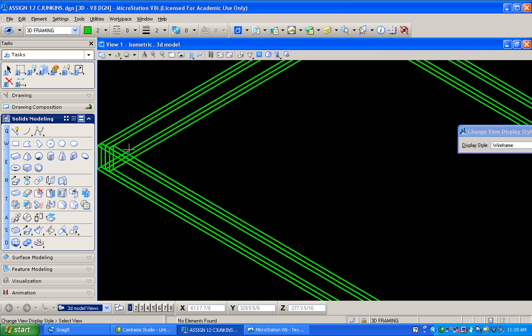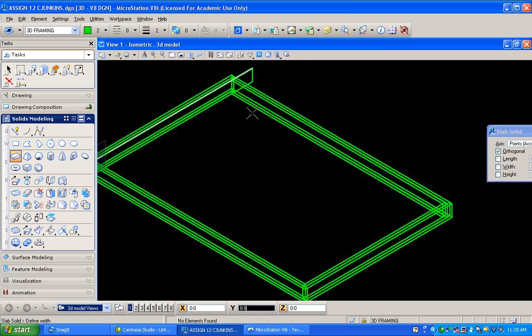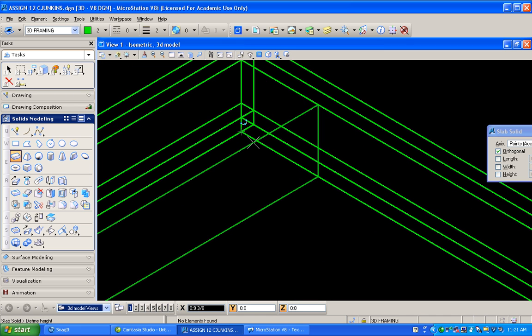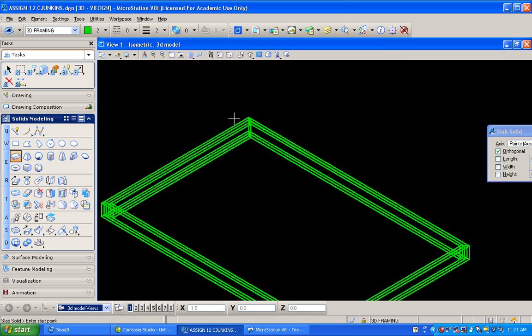joist on this inside. So I'm just going to take my solid block again, copy it, side to inside, and colon 1.5 thickness. Generally, remember our sheets of plywood are 4 feet wide, or 4-foot modules.